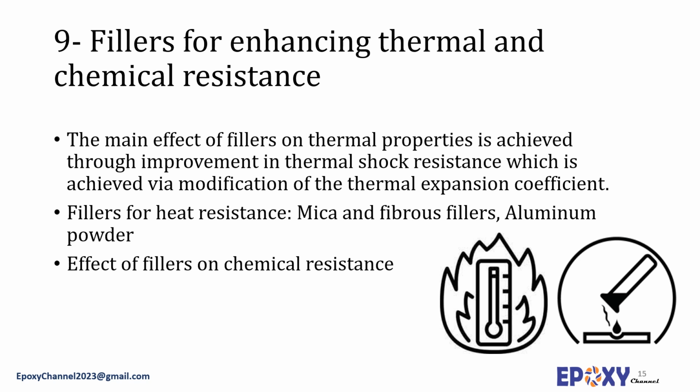Mica and fibrous fillers used in relatively high loading provide very good improvement. However, their use is often precluded due to their handling difficulties. Fillers having high thermal conductivity will also increase the heat transfer in the cured epoxy system. The improved heat dissipation will result in improved thermal cycling properties. Aluminium powder in particular is frequently employed at a relatively high concentration in high temperature epoxy adhesive formulations. The filler provides improvement in heat resistance and increases the thermal conductivity.